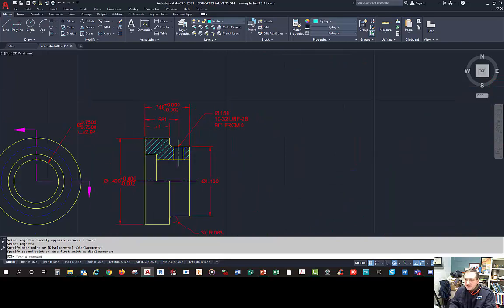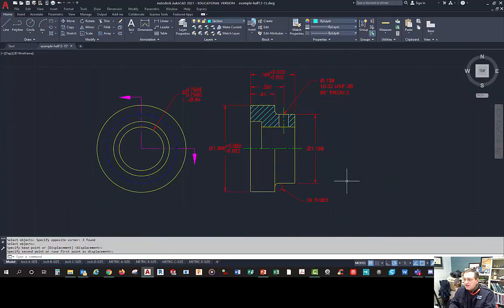Now, one of the reasons that those are showing up is I have the magic triangles on down here. This one you want to have on because it shows annotative objects, and everything we're using is annotated. Text, multi-leader style, dimensioning, okay? Beat that into your brain, please. And then here is your other magic triangle that says show, oh no, I'm sorry, I'm reversed.